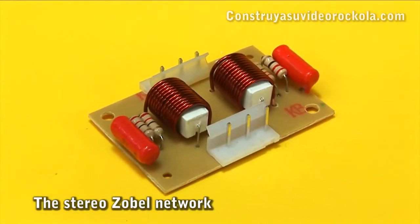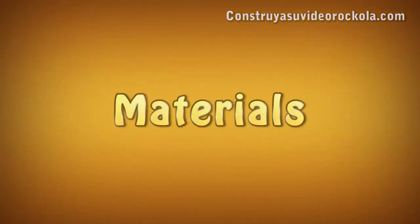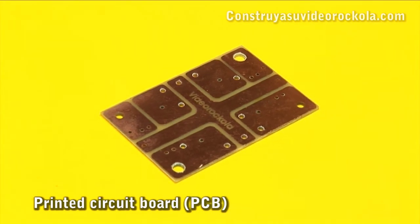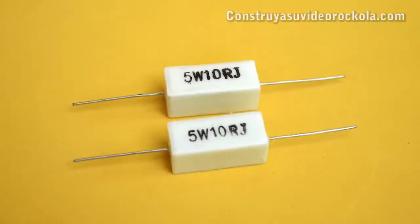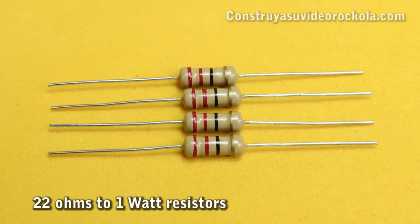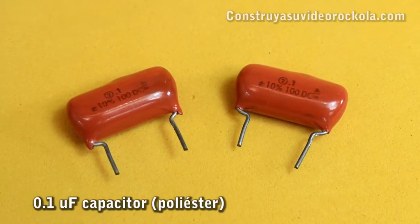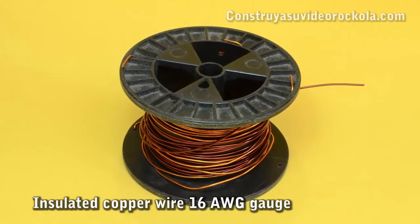Then we will see how to build a Zobel network, serving for many amplifiers. Materials. Printed circuit board, it can be made in fiberglass or bakelite. In the video description, you can download the PDF file. 2 resistors, of 10 ohms, at 5 watts. 4 resistors, of 22 ohms, at 1 watt. 2 capacitors of 0.1 microfarad, at 250 volts. An insulated copper wire, 16 AWG gauge.